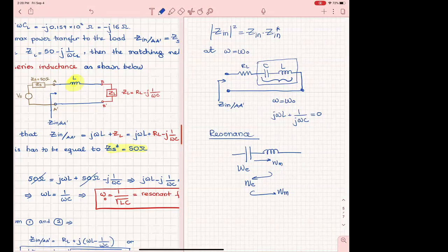But obviously, in reality, that does not happen, because any capacitor has losses through the metal and the material, and an inductor has losses for the same reason, whether it has a ferro material in there, or if it's only the coil, because of the losses in the metal. So if you feed a circuit like this that has been designed with C and L at that particular frequency, you send a wave into this circuit that is resonating.